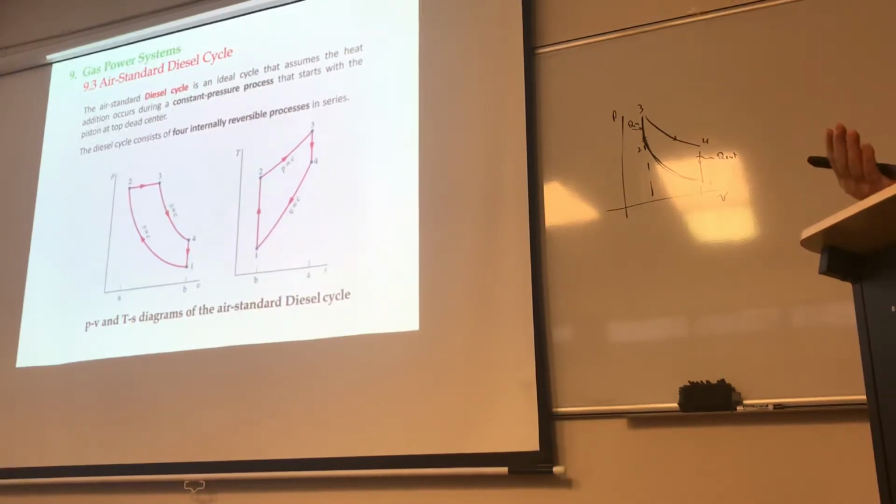If there is no volume change, you're not going to have any work, right? So the only work that happens is really through the expansion in here, right? But how about here? While you are adding heat at constant pressure, is there some work being done? Yes, because it is accompanied by some volume change, right? And you still have some further volume change in here, okay? So that's the only remark that you have to make about this.